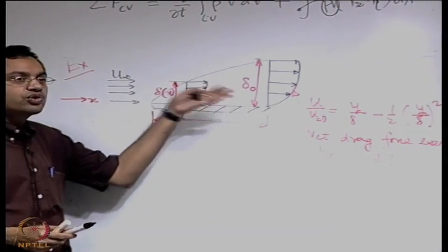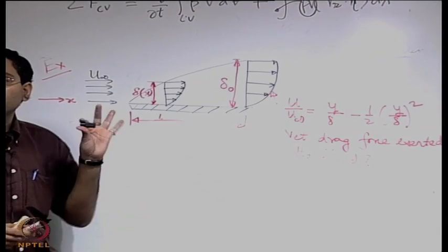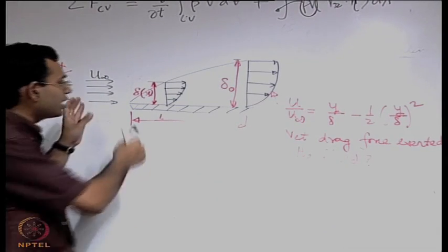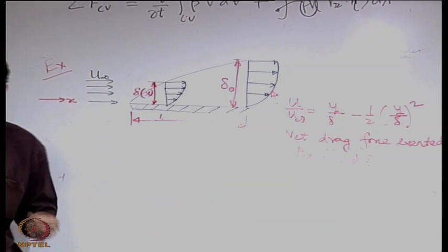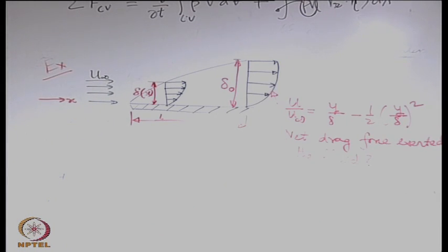This is a physically interesting parameter because of the viscous effect there is a drag force, that is, the plate tries to slow down the fluid, and our objective is to find out what is that net force acting over this length L. Okay. So to find out a force we may understand that we might require a linear momentum conservation because a force is involved, and when we have a linear momentum conservation the mass part of that should also be conserved, so we should also be consistent with mass conservation.